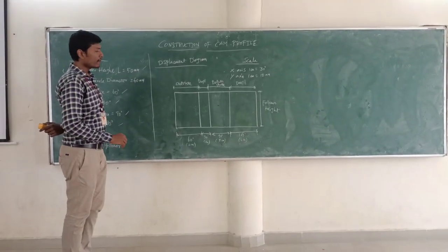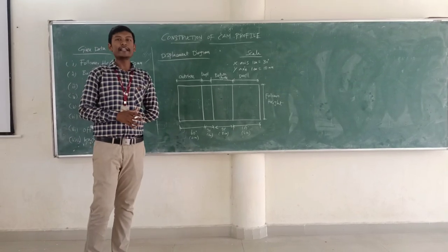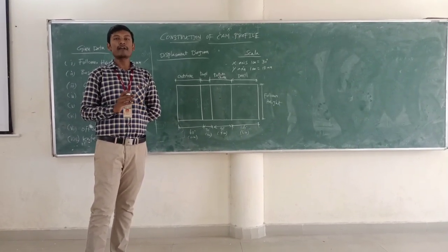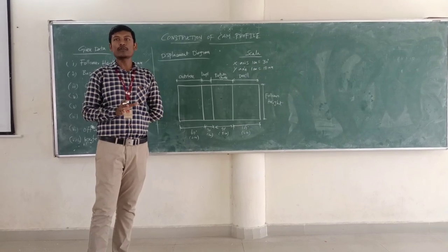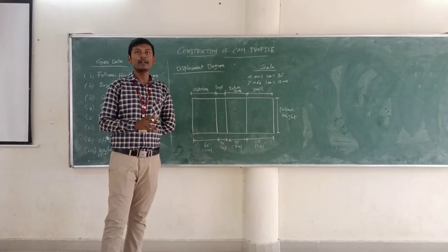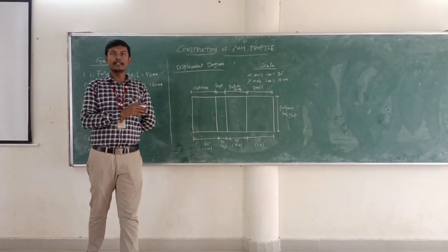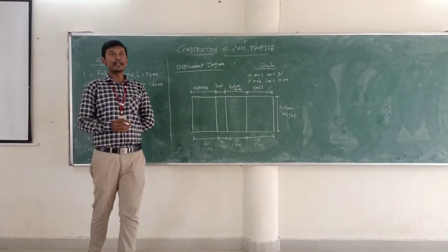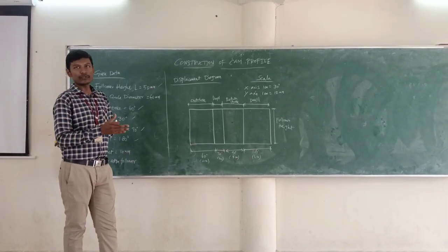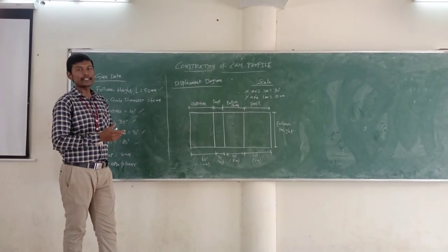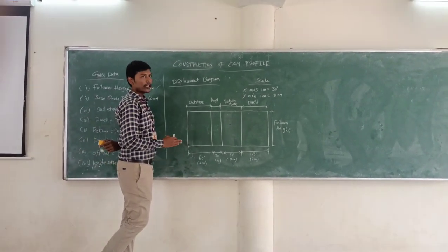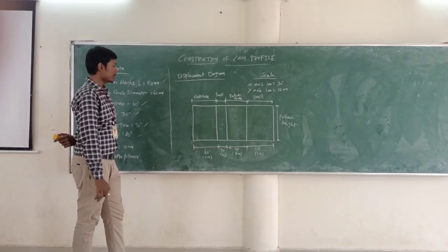So for this case, we need to divide the outstroke as well as the return stroke portion into a given number of parts. During the dwell there is no motion, but in the outstroke and return stroke there is motion. So for that motion, we need to split the two areas into an even number of parts. In order to divide the outstroke as well as the return stroke into an even number of parts, we can take this as two even parts. For the 60 degree, you need to divide that portion into a number of even parts.